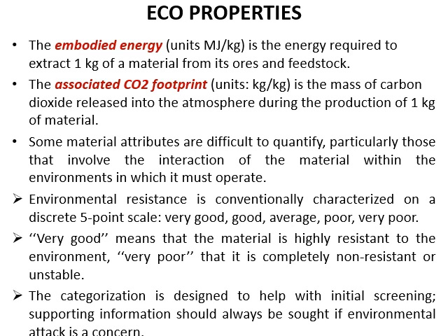Some material attributes are difficult to quantify, particularly those that involve the interaction of the material with the environment in which it must operate. Environmental resistance is conventionally characterized on a discrete 5-point scale: very good, good, average, poor, and very poor.